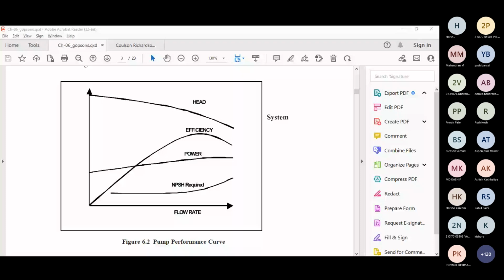Any other questions? Anyone? Sir, I have one question. There is a relation of viscosity with the type of impeller selected. Yes, again it is related to the choking service only. Slurries will have solid content as well as higher viscosity. So with viscous mass or material having a higher melting point, you can go with the open impeller.